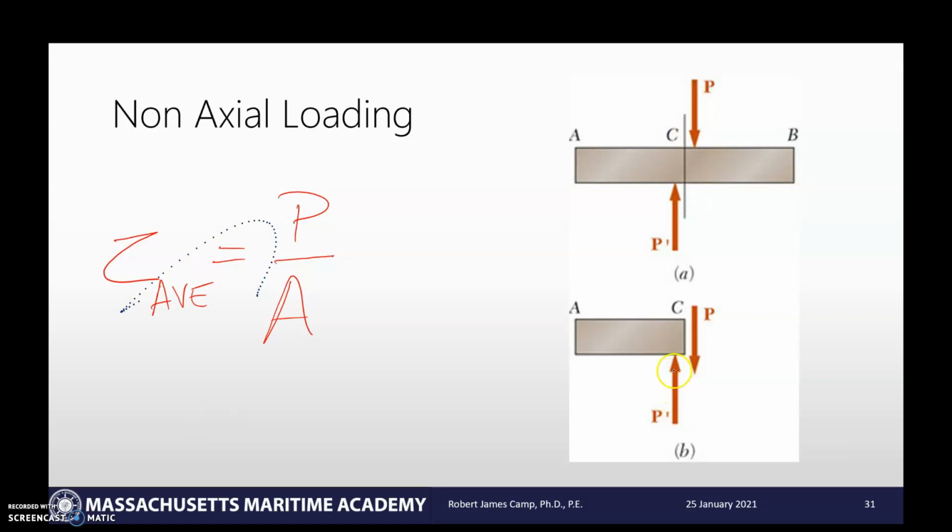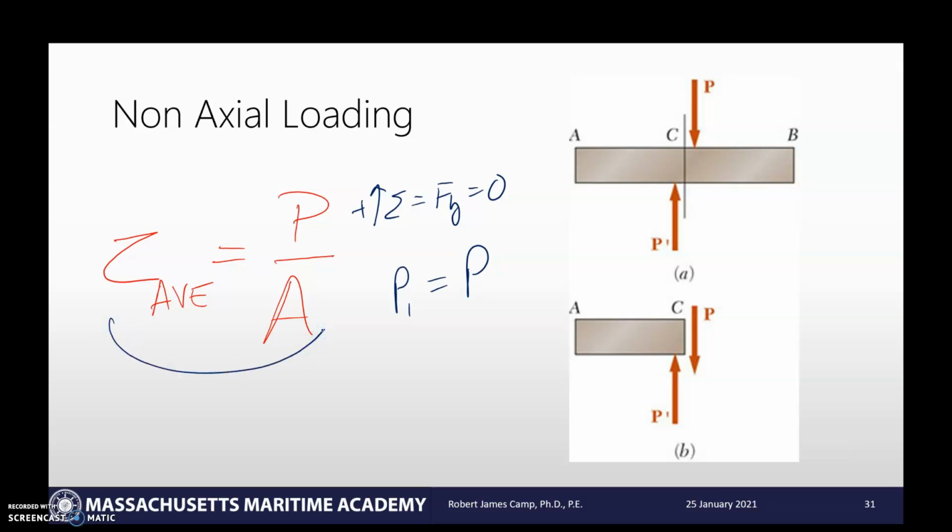We have this load P on the outside. If I do my summation of forces in the y direction equals 0, with up being positive, we are going to have an internal force of P that is balancing out that external force being applied. As you can see here, I left in my notes already, this is where we're going to get our force. And so we've got tau, once again our Greek lowercase tau.